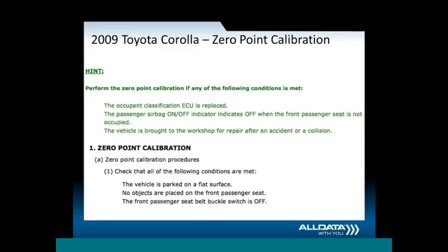And I might like to point out that you have to use a factory scan tool in order to perform a lot of these operations. But again, had I not researched this through AllData, I would not have known it was required. I would not have done a proper repair. Therefore, I would have done an unsafe repair.